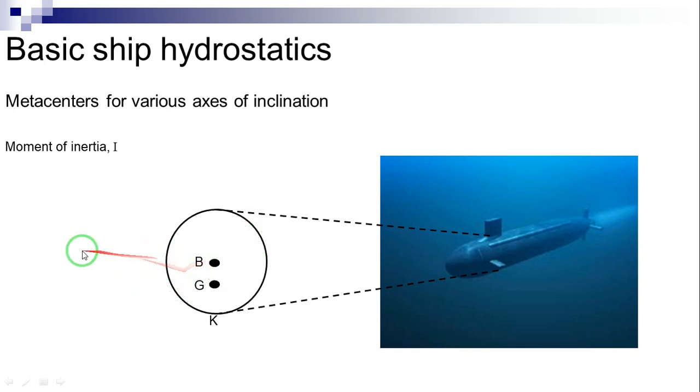In case of a submarine, the righting arm is calculated using this equation. Therefore, the maximum value of the righting arm occurs at 90 degrees. The most critical period for submarine transverse stability is during submerging or surfacing, because of the effect of the free liquids in the main ballast tanks, which are going to be addressed later in this video.